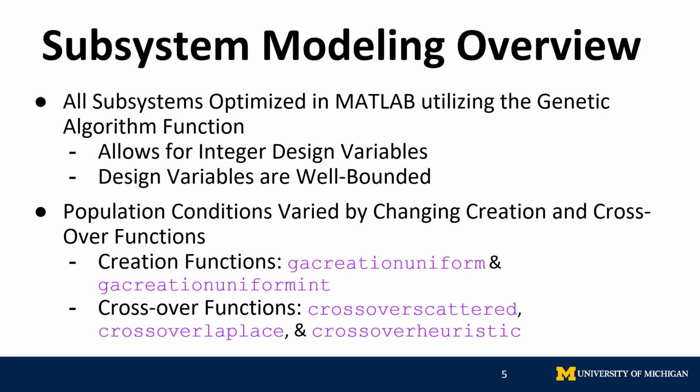All subsystems were optimized using MATLAB's genetic algorithm. This method was selected as it allows for integer design variables representing discrete options. Our design variables are well-bounded, a requirement for using this algorithm. To ensure global optimum results, different creation and crossover functions were utilized to create the initial population and form crossover